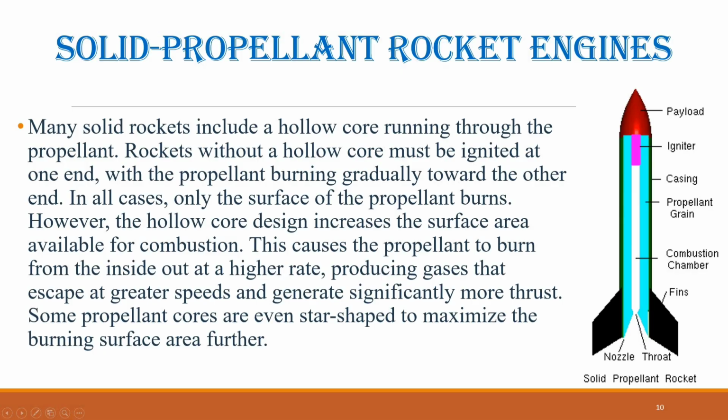This causes the propellant to burn from the inside out at a higher rate, producing gases that escape at greater speeds and generate significantly more thrust. Some propellant cores are even star-shaped to maximize the burning surface area further.